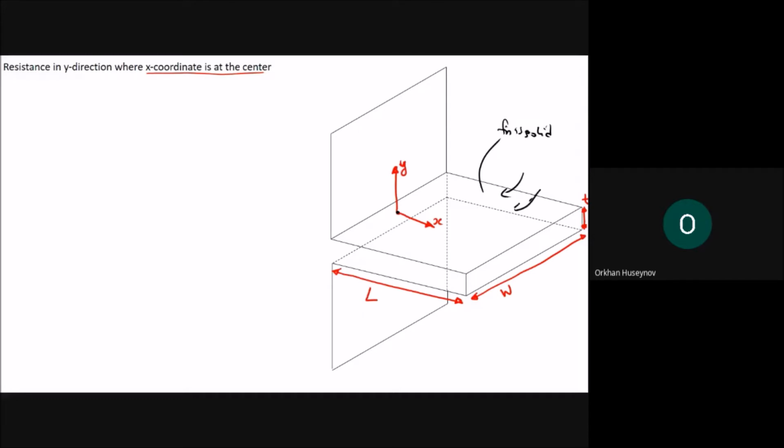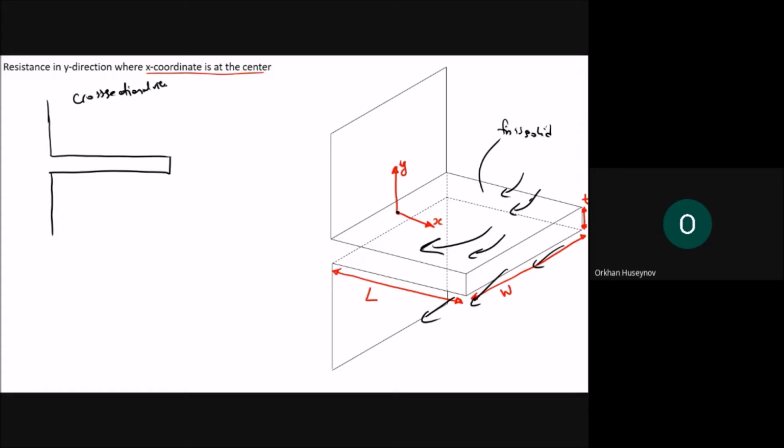And you have the air flowing over that fin, as well as below it. Okay, so here you have also the airflow below the fin. And the resistance concept, if you look at it from the cross section, so you have the fin here. I will show the same coordinates here. You will have this x coordinate and this y coordinate. Okay. And here, if you have the temperature of T1, you will have one resistance here, and you will have another resistance here, and this temperature here will be T2 at the surface, and you will have this T infinity.